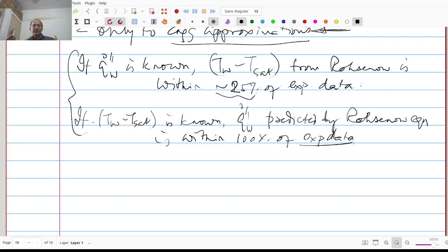So 1300 degrees Celsius is the temperature at which any steel would become softer. And it's not economical also to build power plant boilers using expensive tube material, because in a typical power plant it is known that the length of tubes can be anywhere between 3 to 5 kilometers. That is the length of tubes that are commonly used. So the cost of the boiler will become substantially higher the moment you try to use more expensive materials, and therefore you need to work with a substantially higher factor of safety, right?